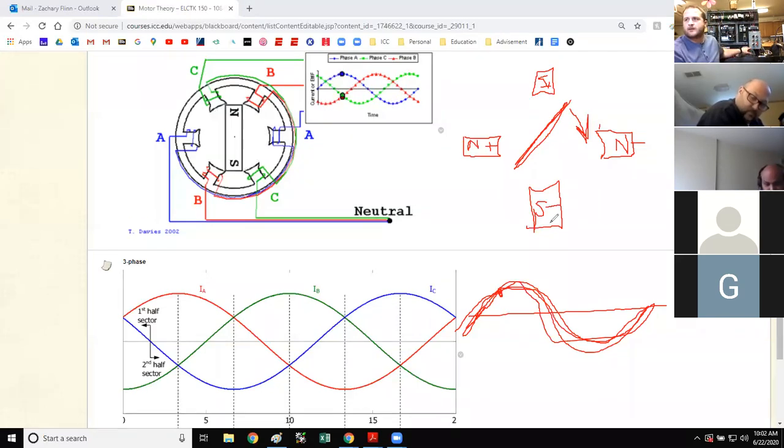Oh, this guy. Yeah, you can see that. When you see a single phase motor that's got this big, looks like a growth on top of it, there's a capacitor. That's a cap start motor. And then this one over here is a 3-phase motor, and we're going to go over how to hook those up next.